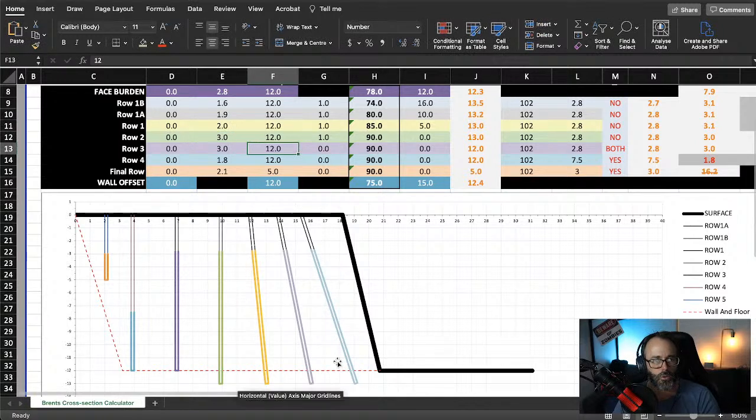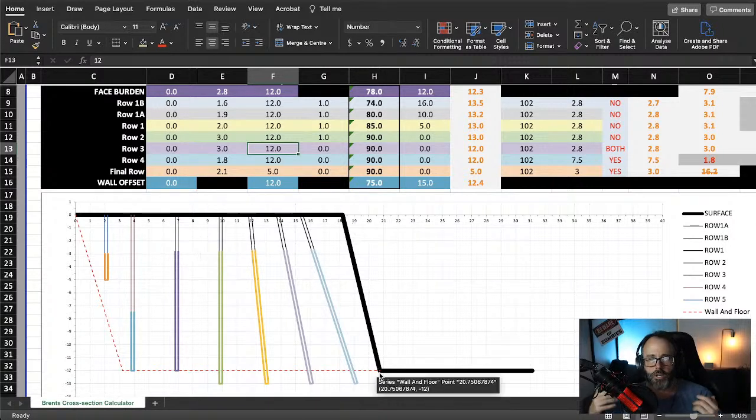Yeah. So as you slowly stand up, going from a high angled face to a vertical hole is very difficult in quarrying. So that's generally why people drill 10 degrees across the board or 5 degrees across the board, because they know what their face is going to break out at, and if it's religiously breaking out at 10 or 12, then they'll set their main body of the pattern. There will be their site specific parameters for that, and they'll set it at 10 and slowly progress back.